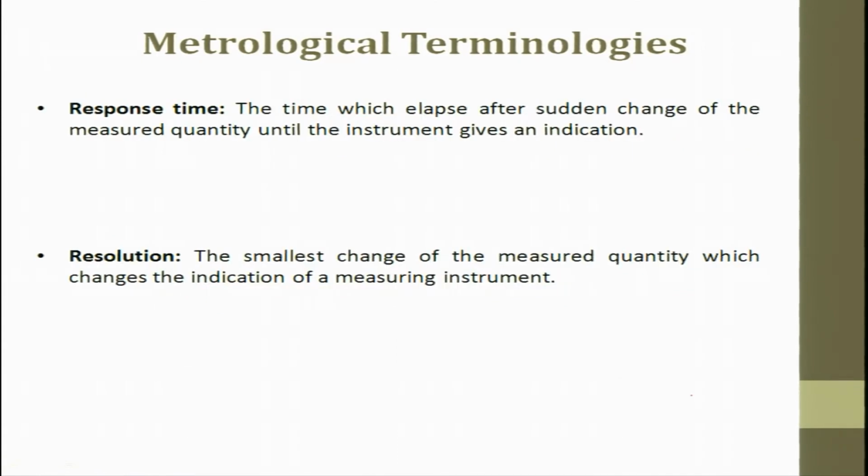What is response time? The response time is the time which elapses after a sudden change of the measured quantity until the instrument gives an indication. So, response time is like I give you a command, how quickly you respond. If there is a change in the measuring device or the measurement value, how quickly can this change be responded to or recorded? That is nothing but response time.